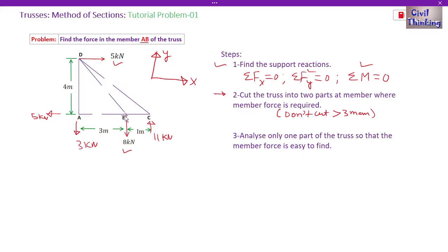Now in step 3 we have to analyze only one part, either left or right. Let me analyze the left part. First we have to assume all the forces in the cut members are tensile. We have to assume all the member forces are tensile. The members which we cut, we will assume the forces in them to be tensile.